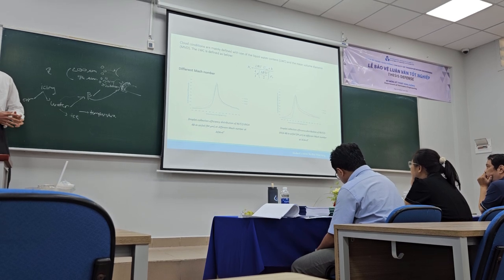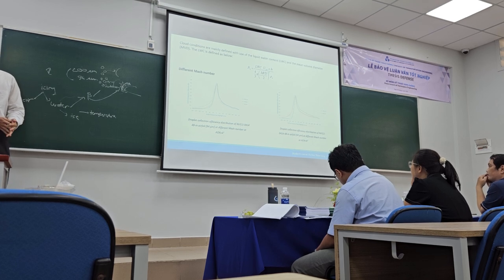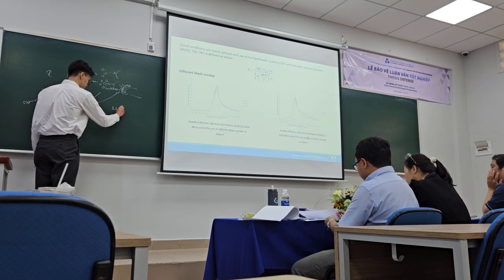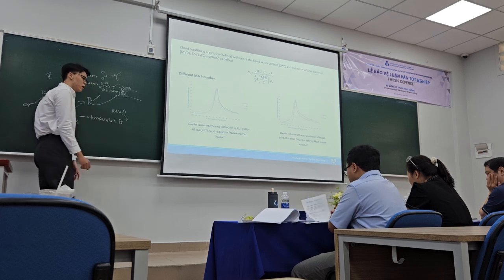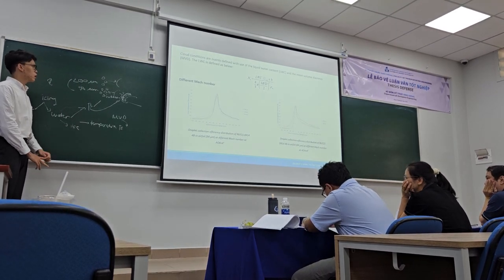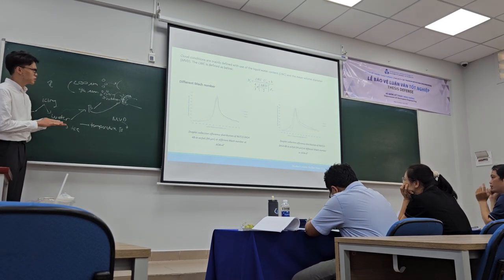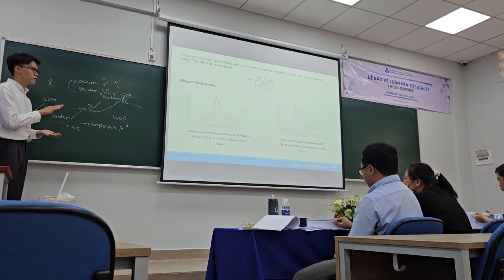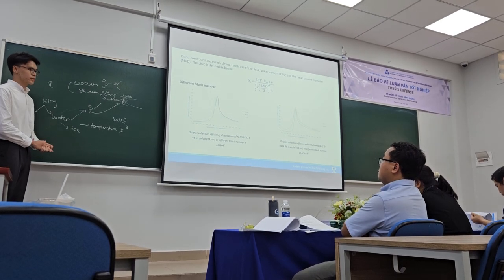So with the third question, from the surveys at 0.8 Mach, which parameter affects the beta the most, I suggest it will be the medium volume diameter, MVD, because in the formula to calculate the beta coefficient, we have the effect of MVD. So this will affect it the most. But the velocity or different angle of attack just changes how the droplets hit the airfoil surface, on the upper or lower surface.